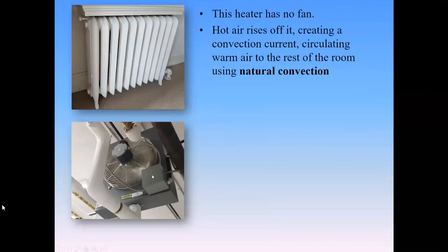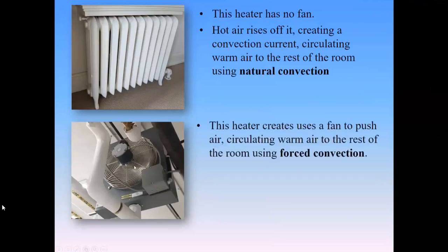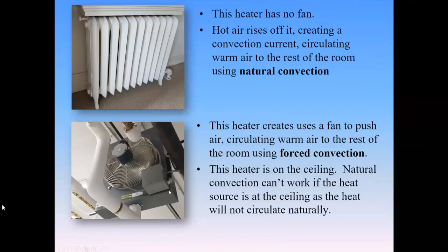This one, in comparison, is set up with a fan. So in behind we have a heat exchanger, and we have a fan to push it. And the reason why we have a fan is, one, this guy is mounted up on the ceiling. Okay, so we have this heat exchanger that's on the ceiling. So we know that natural convection isn't going to work if our heat source is up high.